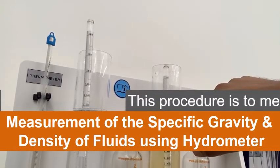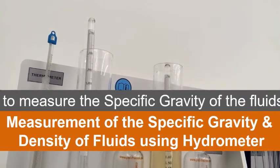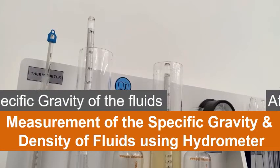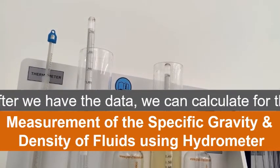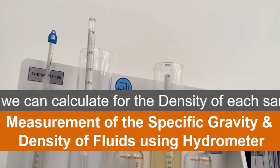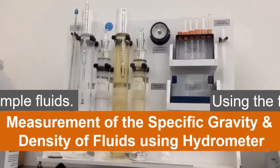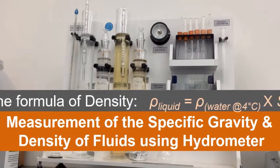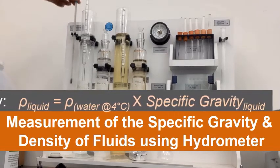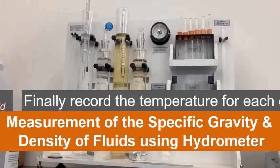So this procedure is to measure the specific gravity of the fluids, which we'll use to find the density of these fluids in our table. So we'll take the temperature of each of the fluids, then we can record the data which we'll use in our table.